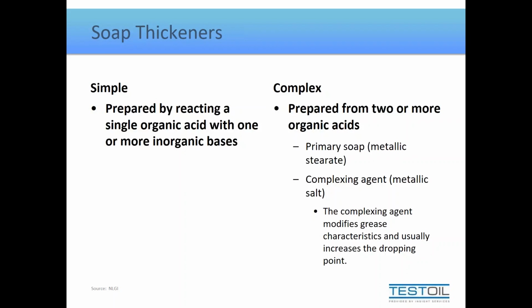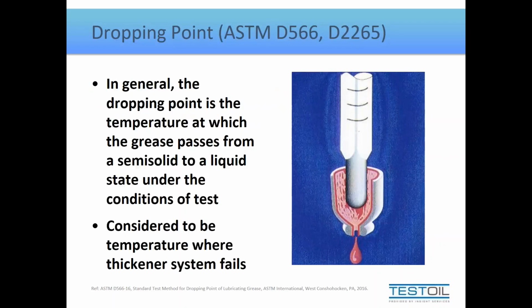So to cover that, let's look at the dropping point test briefly here. The dropping point test is a test where we heat a small portion of the grease and we see at what temperature we will get a drop of oil to extract.